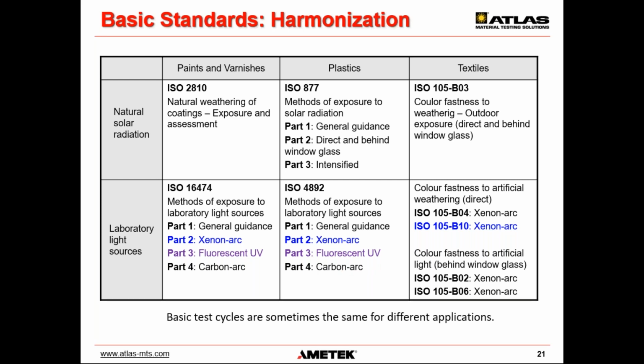One thing to note for those of you who are familiar with the ISO coating standards: the ISO 16474 series of standards has replaced the former ISO 11341 and ISO 11507 standards. I also mention harmonization in this slide because many of the standards, more specifically those using laboratory light sources, have very similar standards across different applications. For example, in the coatings, plastics and textile industries, the xenon arc standards are very similar.